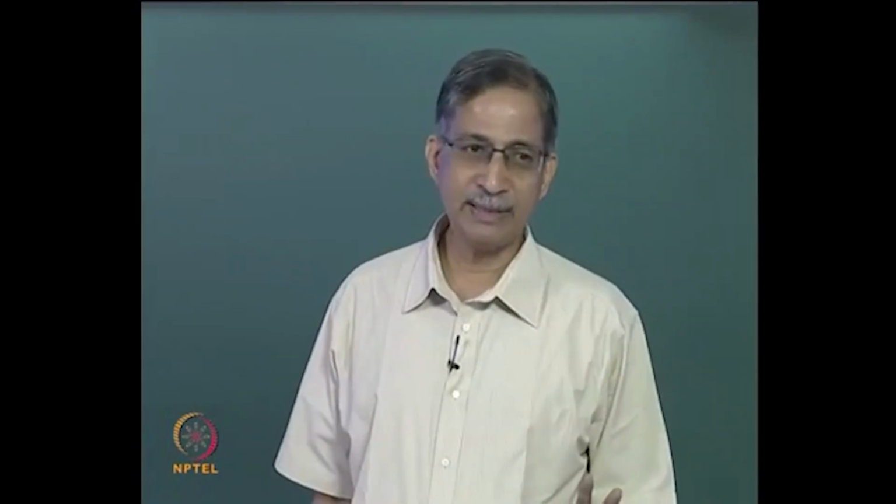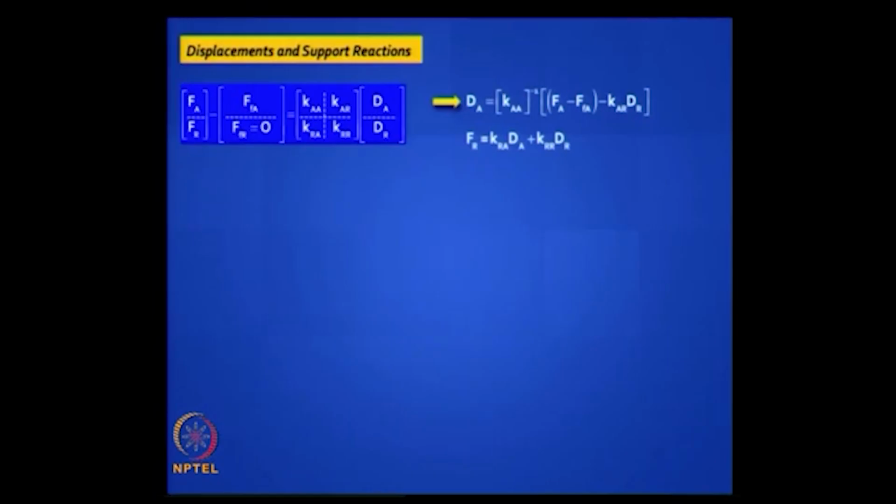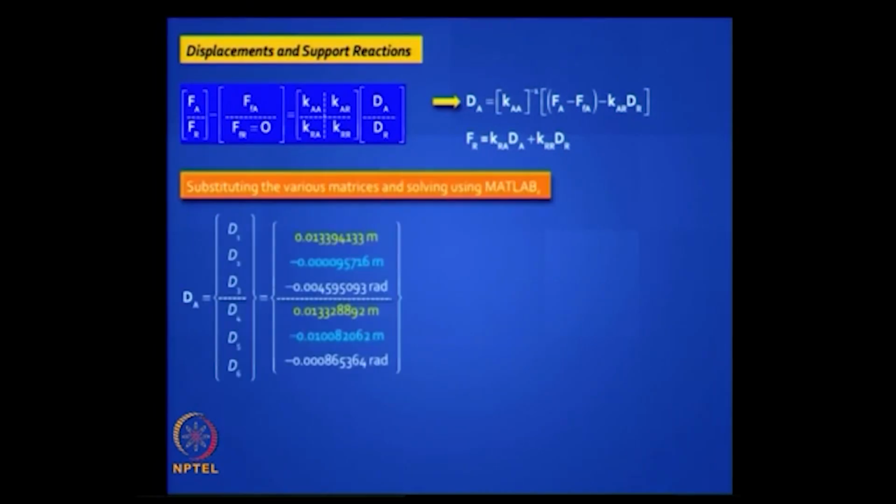Next step is very clear. You have got your structure stiffness matrix, you have got the transformations, you have got the net load vector, you have this familiar equilibrium equation, and you plug in those values and you can find the active displacements by solving that equation. You take KA inverse, the computer can do it for you.